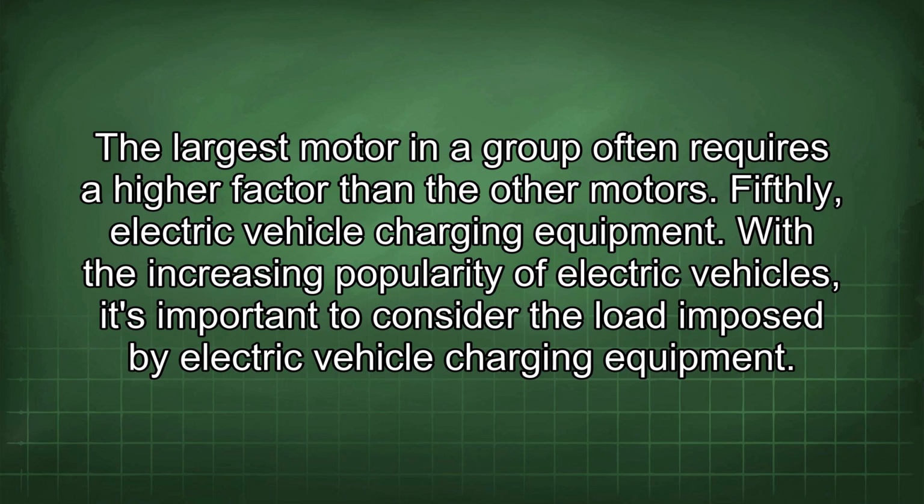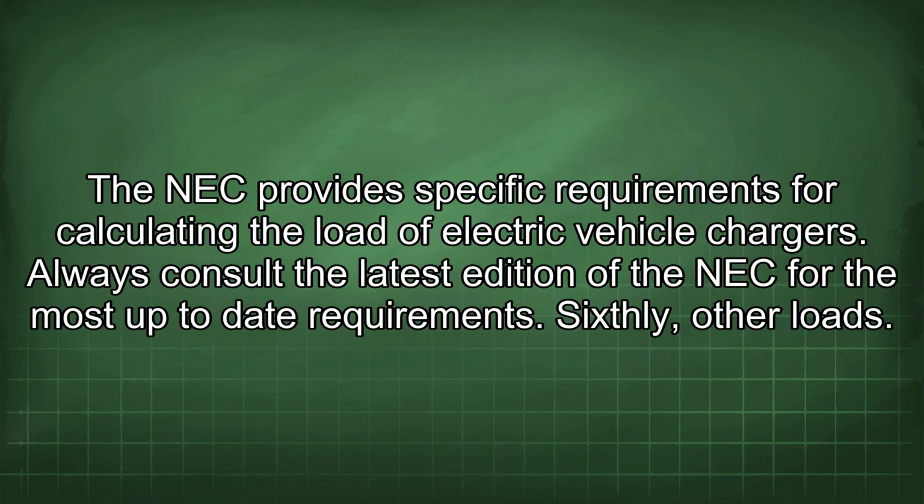Fifthly, electric vehicle charging equipment. With the increasing popularity of electric vehicles, it's important to consider the load imposed by electric vehicle charging equipment. The NEC provides specific requirements for calculating the load of electric vehicle chargers. Always consult the latest edition of the NEC for the most up-to-date requirements.